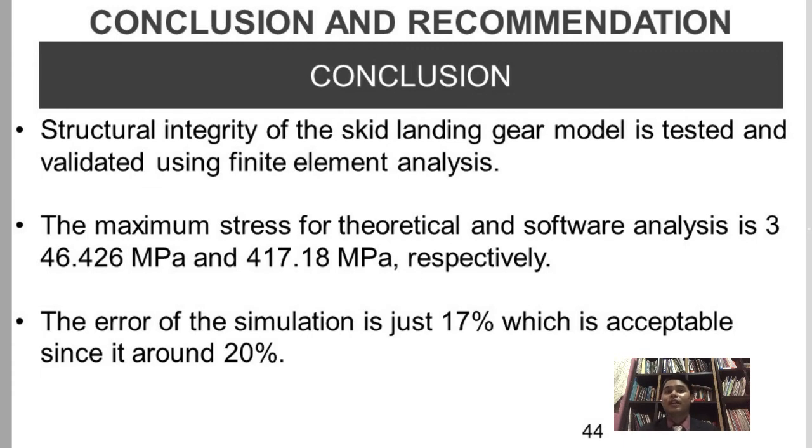Okay, in the conclusion, the structural integrity of the skid landing gear model is tested and validated using finite element analysis. The maximum stress for the theoretical and software analysis is 346.426 megapascal and 417.18 megapascal respectively. The error of the simulation is just 17%, which is acceptable since it's around 20%. However, this error might be due to the computational restriction that the convergence cannot go down to 0%. Still, it can be accepted because it's around 30%.